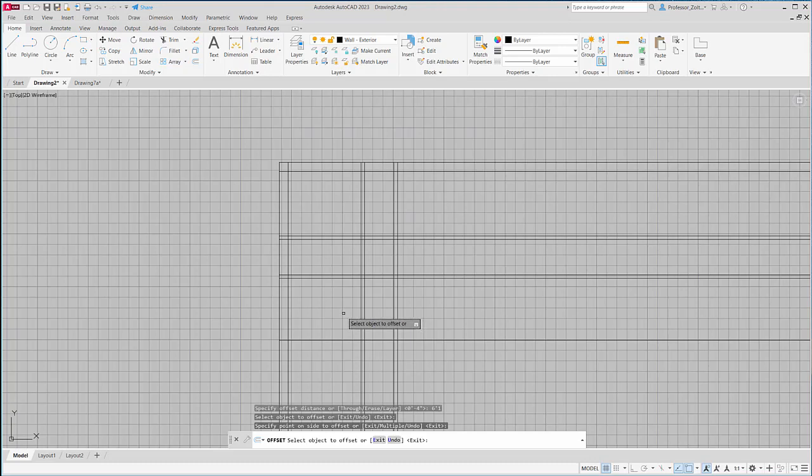All right. Here's another thing we must consider when we're looking at inch values. A 1/4 inch is 0.25 inches. A 1/2 inch is 0.5 inches. So if I select offset and I type in 8.25, press enter, that is my 8¼ inches. You can see it in my cursor right now. So 0.25 is a 1/4 inch, 0.5 is 1/2 an inch, and so on. So I've got all my walls, my values that I need along this line.